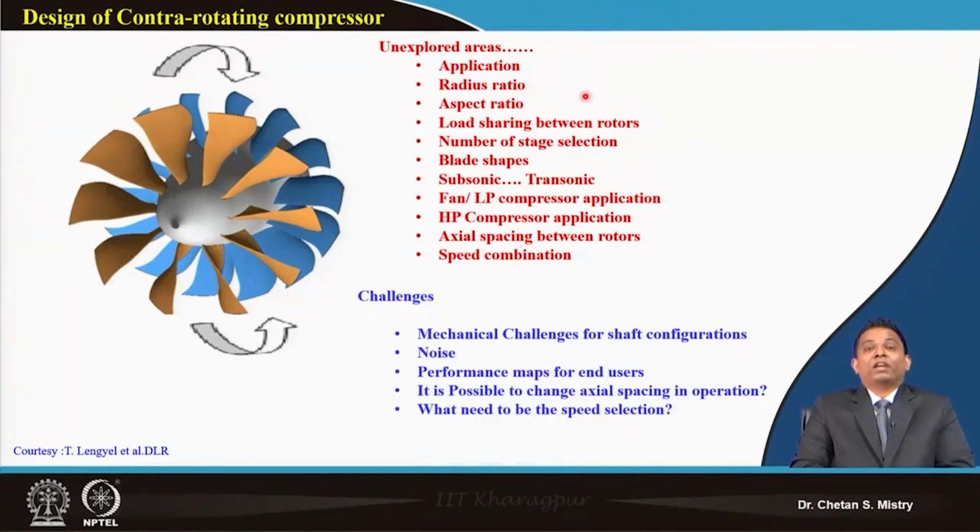When we say my second rotor, that is what is rotating at the high speed, that is what is giving a strong suction effect. Suppose if we are putting it very nearby, it may be possible that the wake coming out from my rotor 1 will be striking rotor 2 very intensely, and that will lead to increased noise. So, noise is a major issue. Then you will think of increasing the axial spacing between two rotors.